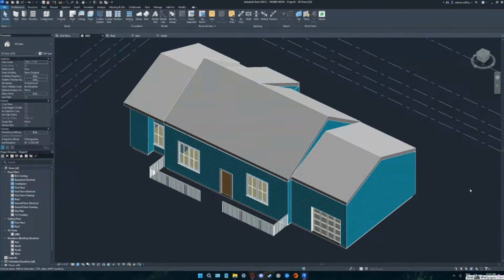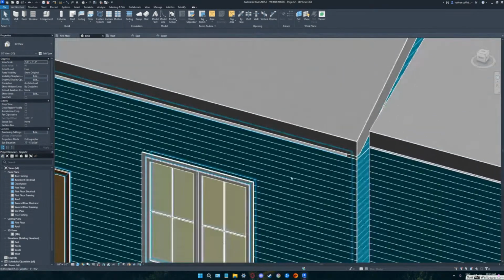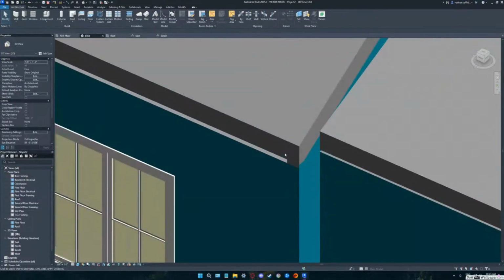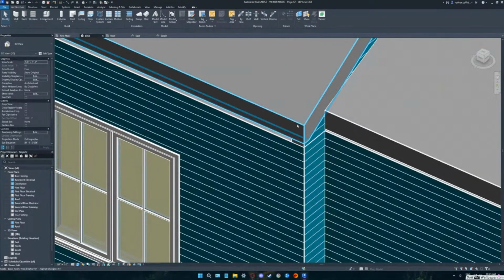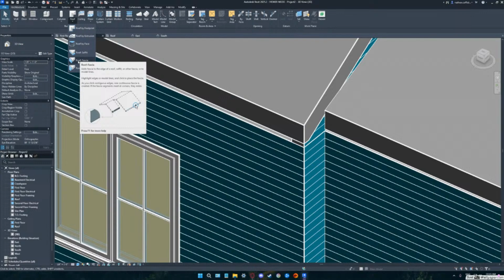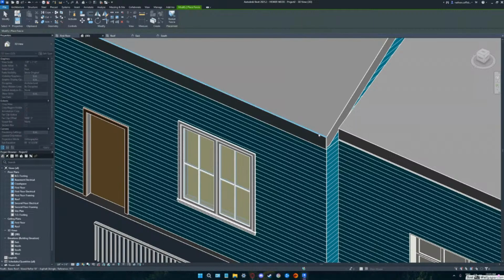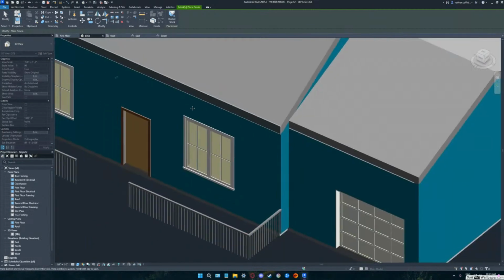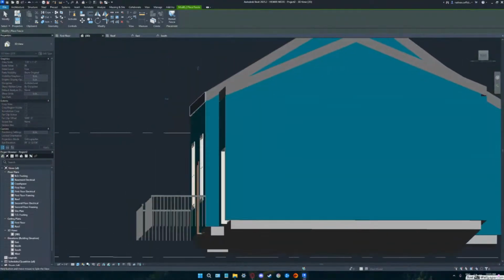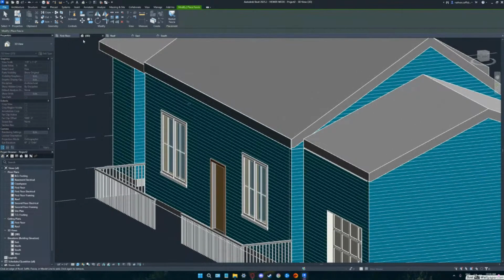Let's zoom into one of the edges of your roof. Typically what we do at that roof is if you look underneath the roof command, the arrow underneath it, you should add a fascia and then potentially a gutter. So go ahead with the fascia first. Try picking the top edge of that roof right here. And click. And you see what it did? It just put a little piece of board on the end of that. See that little piece of board? And then you want me to add.